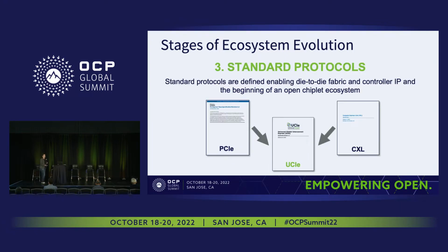So then the next stage is how do we overlay standard protocols? If you take a look at the UCIe standard, they've already overlaid PCI Express and CXL. Now, as we think about it, there's also the challenge of, is that enough? If I look at, do I want an AXI or a CHI mapping? What are the mappings that I need in order to be able to build interesting building blocks? Because PCIe and CXL may be a little too heavyweight protocols for certain applications. So how do we evolve and get the standard protocols on top of those physical interfaces that will really carry us forward?